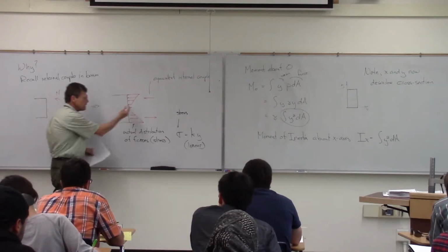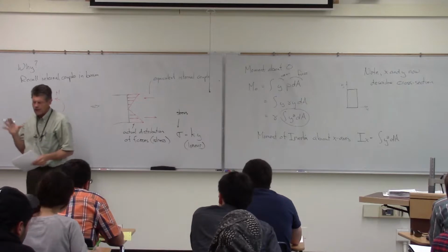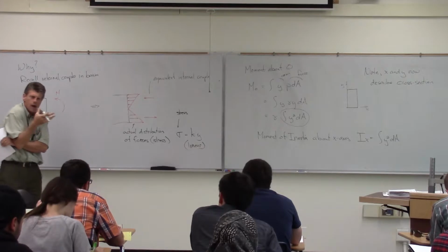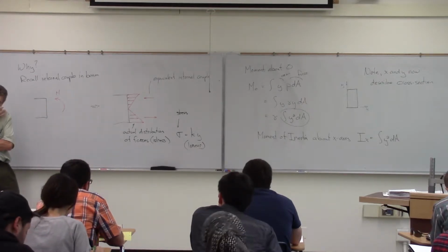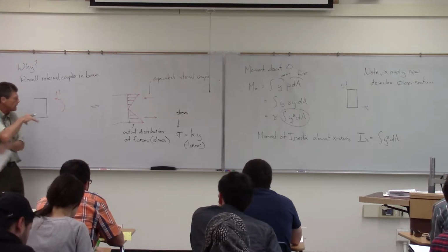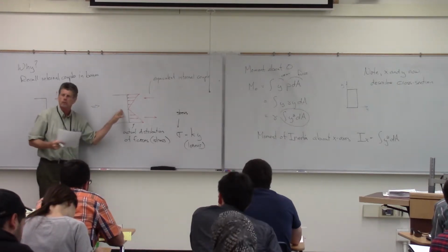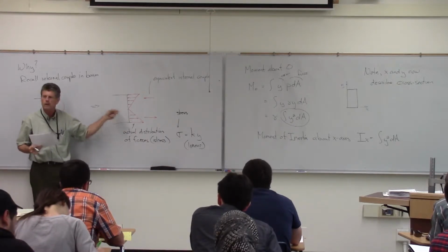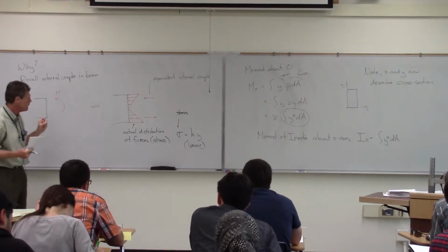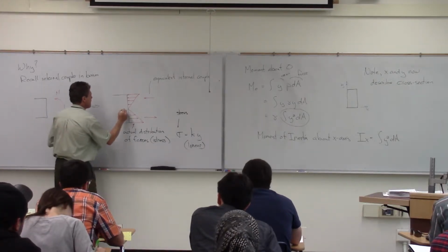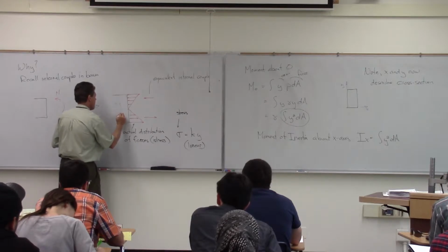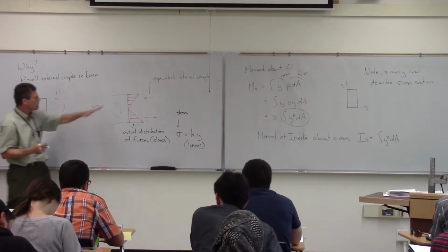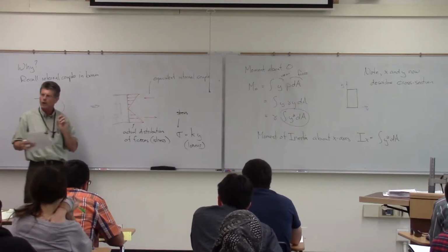So what we're going to find then is in beams and in the range of the beams that we're designing and that sort of thing, we're not talking about rubber beams, but when you think about concrete, when you think about steel, visibly you're going to see maybe a little bit of bend. But what we're going to find is that the distribution for the most part, for most of the areas that we're designing for, is going to be this linear distribution. And the way we're going to be able to describe that is with this magical little term called the moment of inertia.